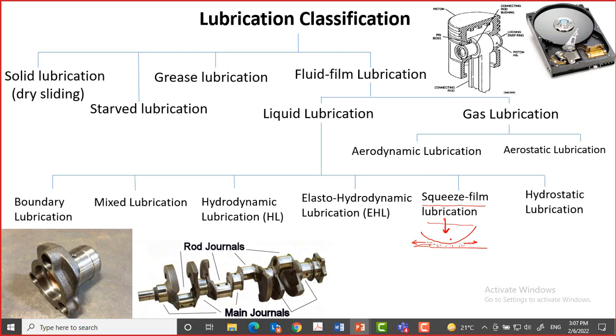When the two surfaces are coming together, because of the movement of one surface closer to the next surface, the gap here will be reduced and the liquid will get squeezed out. Therefore there can be a dry state here, and this kind of dry state will not be good because it will lead to immediate adhesion between metal surfaces, and there will be adhesive wear.